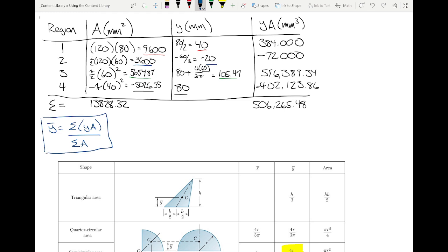and if you're wondering what this is, it's basically just a weighted average. The idea is that if I wanted to idealize the weight of this little bracket, I could idealize it as a single vector at the coordinates of the centroid. What are the coordinates of the centroid? Well, we know the x bar coordinate. Now we can compute y bar.